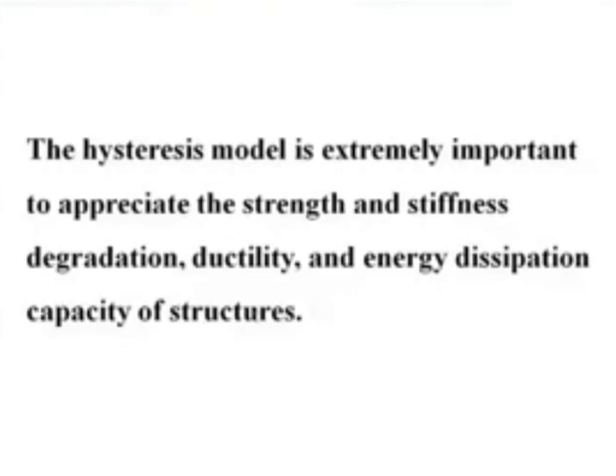And its post-yield behavior will change. And that will result in some level of ductility which may not be acceptable to you. The energy dissipation capacity of the structure.